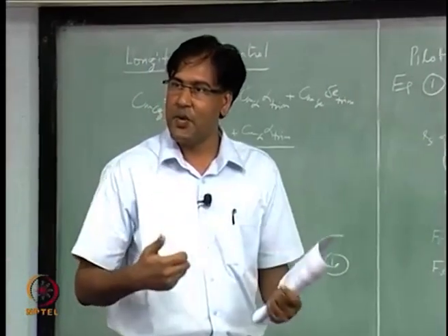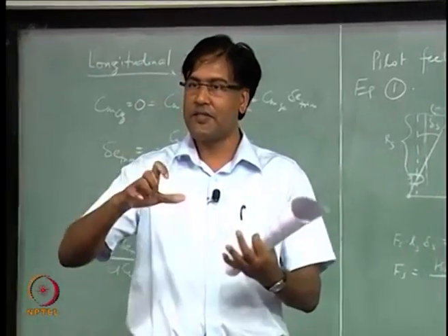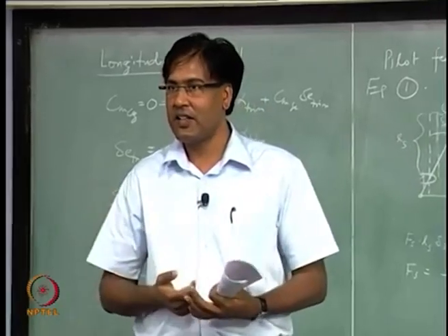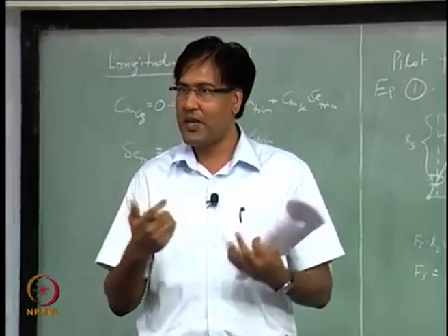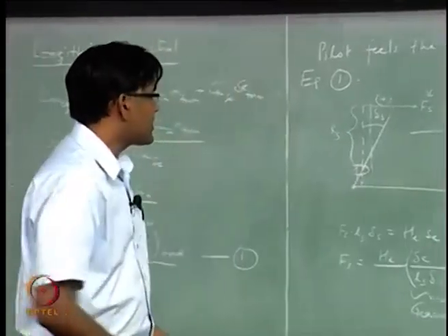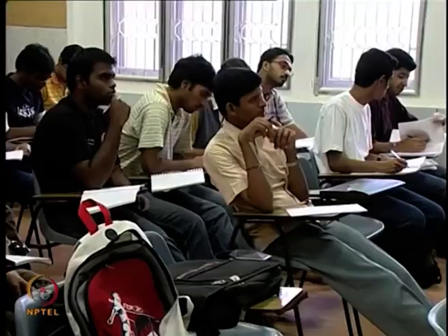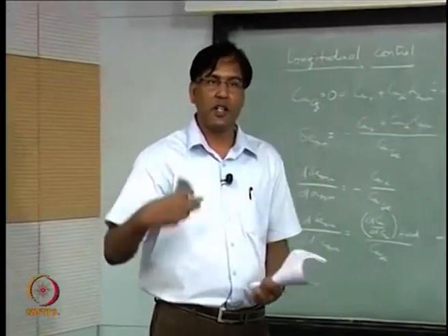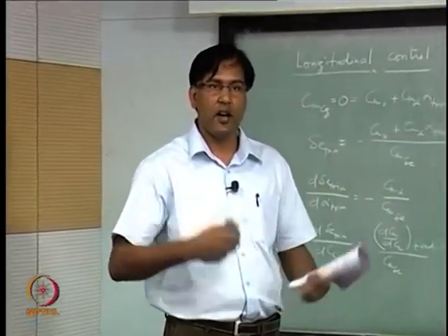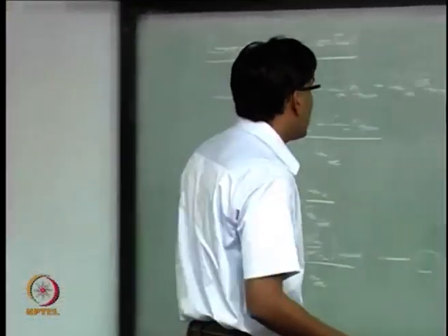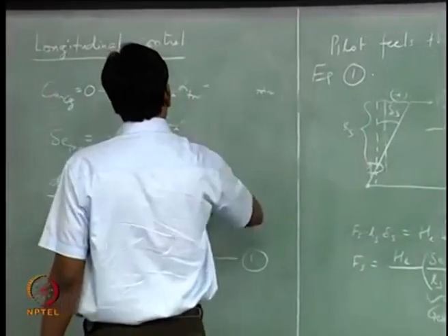What will happen to the hinge moment? If something is allowed to rotate freely, what should happen to the hinge moment? 0, right. So, let us look at what happens in such a case when the elevator is not fixed, but is free to rotate, right. You are not holding the elevator somehow.